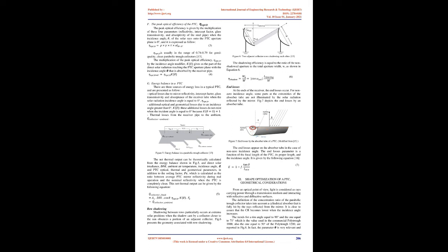Therefore, in addition to the losses due to the angle of incidence, there are other losses on collectors that can be correlated to the angle of incidence. These losses are due to the additional reflection and absorption of the glass envelope as the angle of incidence varies. The incidence angle modifier, IAM, corrects these additional losses of reflection and absorption.